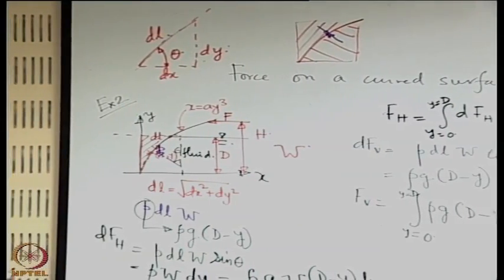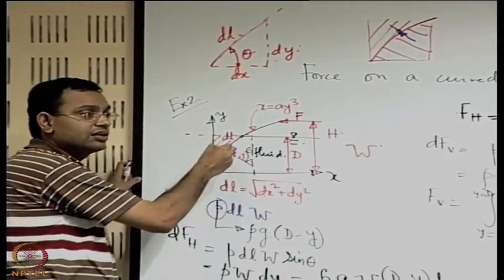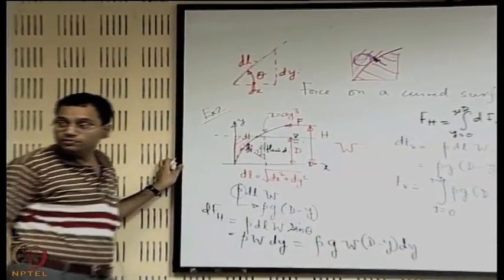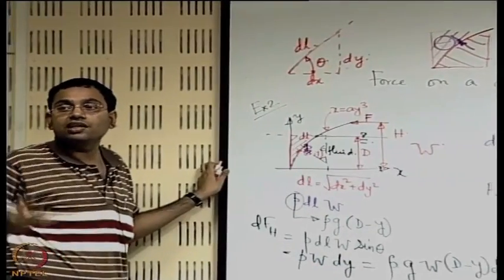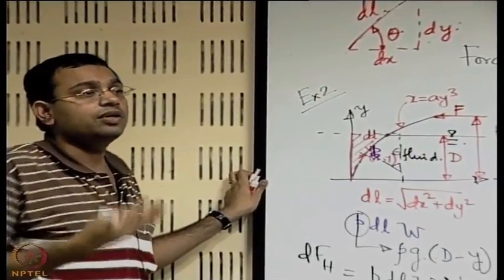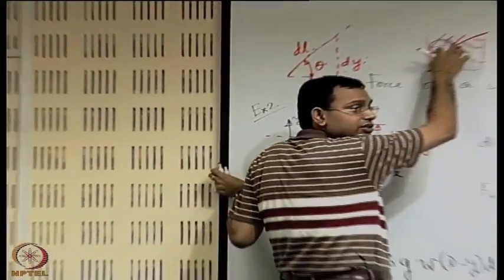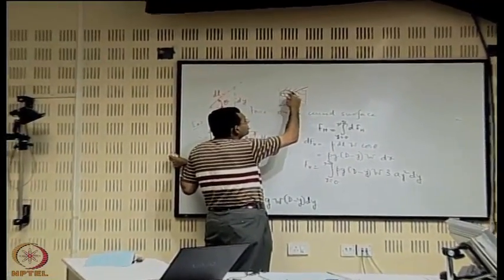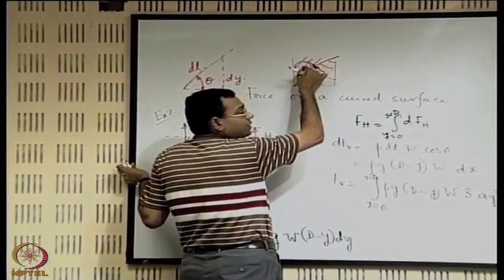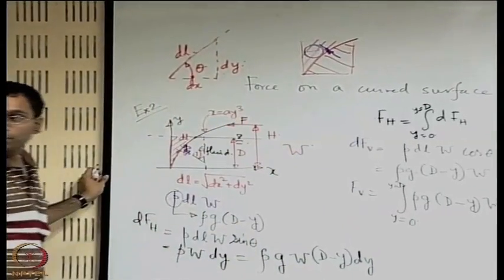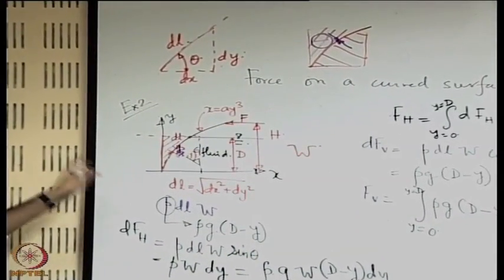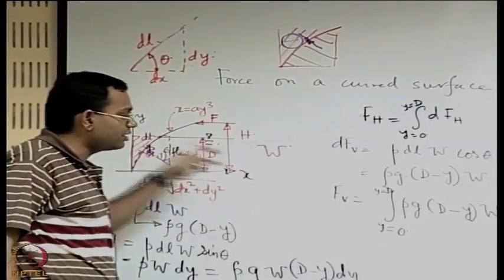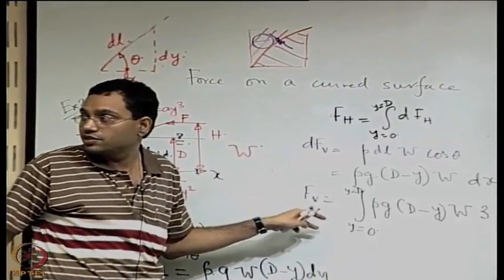Now when you do not have a fluid here, that means that this part is like minus, it is subtracted. So it is a condition equivalent to a deviation from equilibrium because of a lack of presence of this, rather than the real presence of this. So the deviation from equilibrium is because of this equivalent volume of element which is in the upper part. Okay. So if you calculate that volume of fluid and find the corresponding weight of that, you will see that you will get it exactly the same as this one.